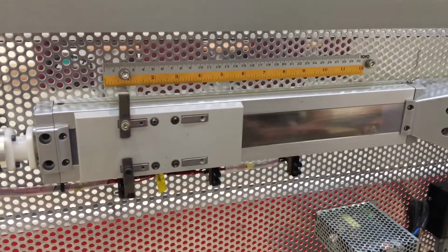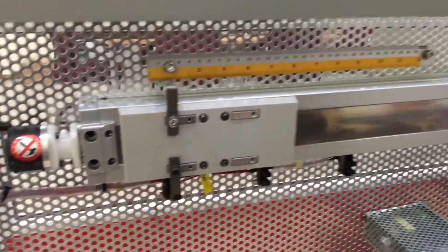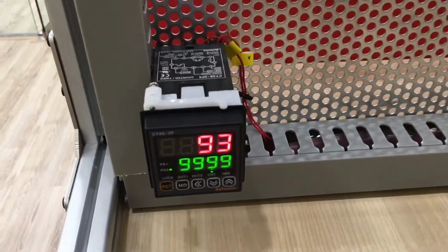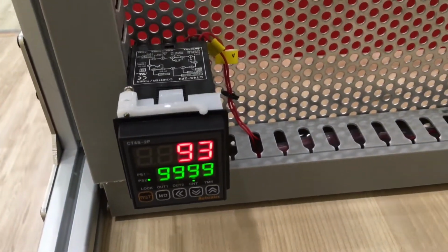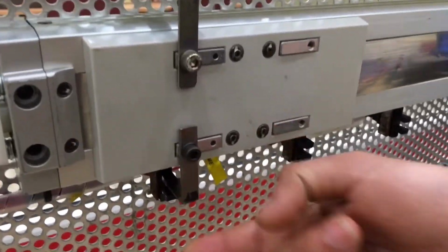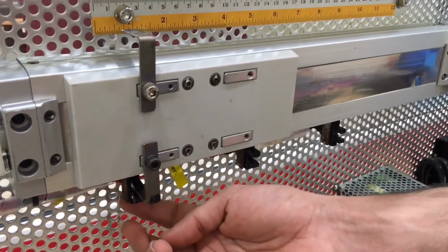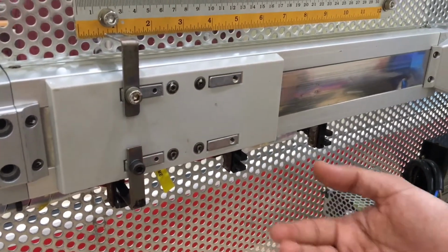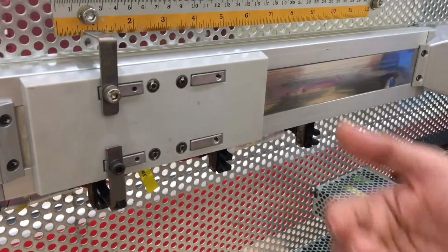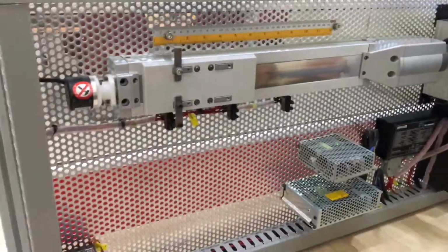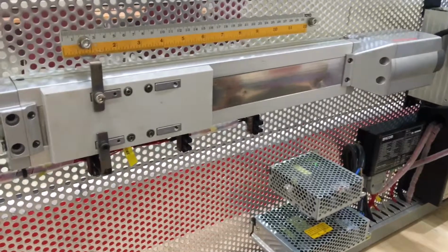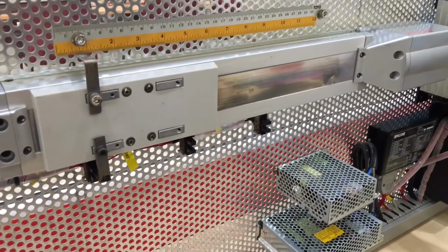XR9. It moved. As you can see in the counter, it didn't show entirely 100. It should be 100 because we moved 50 plus 50. Because we have the sensor over here. Now this is the forward sensor, which stops the machine once it reaches this limit. It's much safer to use the sensor to stop the machine from continuing to an over distance of the motor itself. So this is how it goes, and it should work.